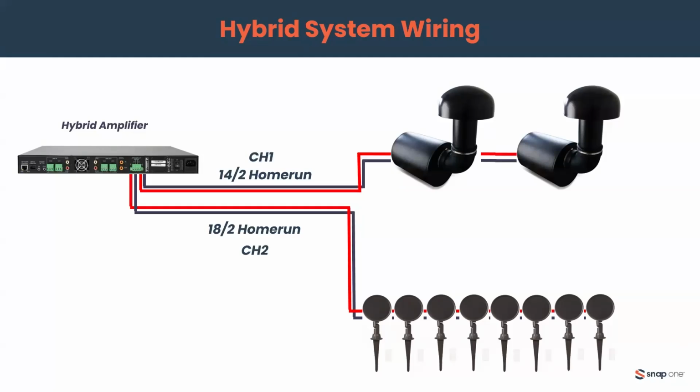And again, add a second subwoofer if you want, if the area is large enough, because they're 8 ohm subwoofers. Again, the amp is 4 ohm capable, so you could actually daisy chain 2 subwoofers pretty safely.